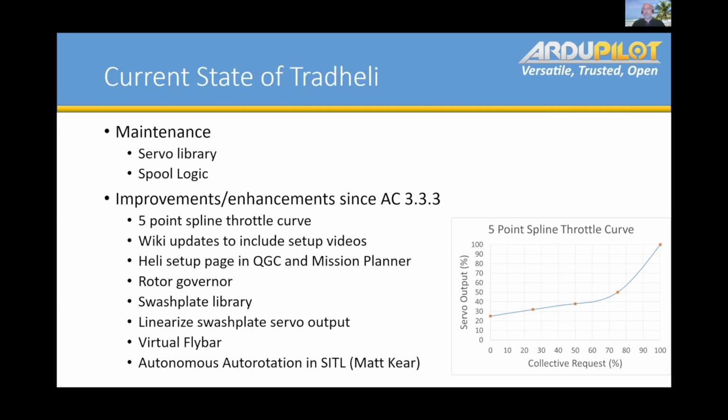First thing we started diving into is kind of maintenance type stuff. I worked with Tridge on the servo library, getting that up to speed, bringing the trad heli portion of the code up to speed with the rest of it, because Leonard and Randy had kind of forged ahead with this spool logic, and they just put little snippets of code inside the trad heli just to make things happy. But basically, they said, hey, now that you're in here, do some work, get the spool logic up to date. So that was a big advancement, bringing trad heli up to speed with spool logic, and that went into 4.0.